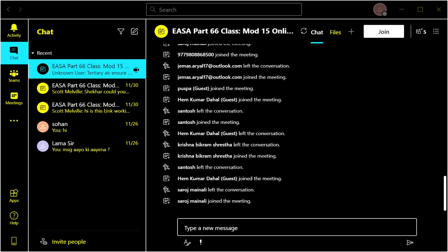And attached to the tank, you might have a filter assembly. So although in the diagram it shows it all over the place, actually it can be quite compact, very close to each other. High pressure pipes tend to be smaller, and your return scavenge pipes tend to be bigger, hence the bigger pump. And there we go, there's a system relief valve. So again, it's all quite close. In the schematic it shows you quite far away, but in the real world it's very close together. It might even be attached to the same thing. The pump could be very close to the tank. All right. Filter bypass, there we go. There's another oil line from the cooler, and also some have a drain for the filter as well.